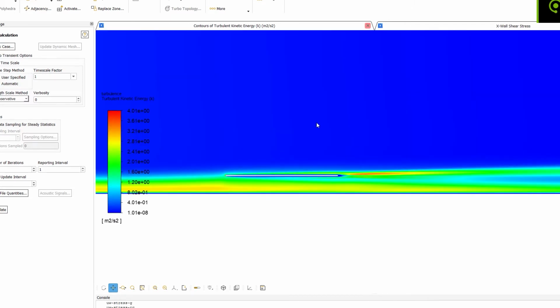LEBU devices have proven to reduce drag against a smooth wall. However, the drag introduced by the device tends to be greater than that of the reduction. A net drag reduction, where drag introduced is less than drag reduction, has not been reliably produced to date. The original goal of this project was to test a LEBU against a rough wall to see if a net drag reduction could be produced.